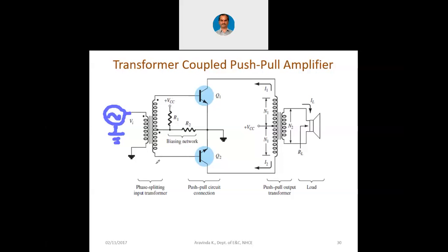Now because of this center tapped transformer, you can see these dots. The dots indicate the commencement of the turns that way. Now always the turns will be wound in this manner, winding will be in this manner. Now when we take a center tap at the middle, automatically you can see the upper side winding has started here and the lower side of the winding is starting here. Naturally these two will be having opposite inductions.